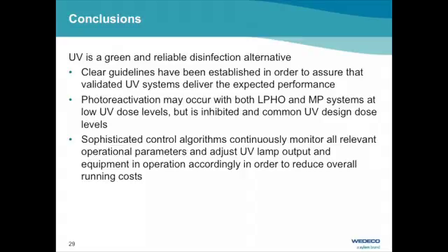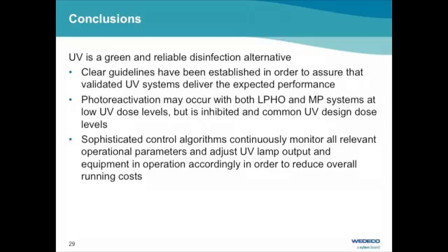So therefore, I would like to conclude that UV is really a true alternative to chlorine, and that there are guidelines by now established which assure a safe system design, which give you the reliability you want to have, that the performance is okay, and that photoreactivation is taken into account when designing the UV system for appropriate dose levels, and that sophisticated control algorithms allow you proper performance monitoring and assurance, as well as reduced operational costs.